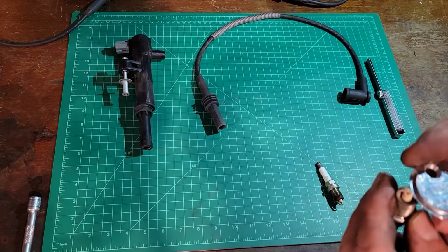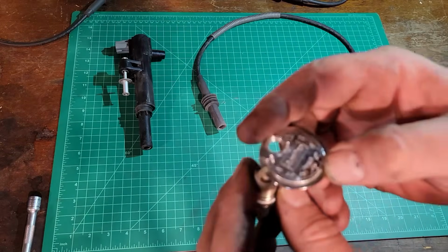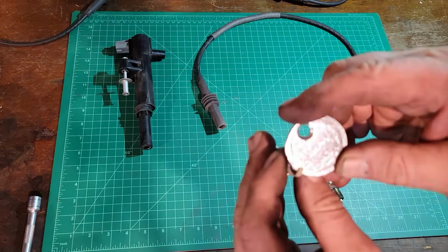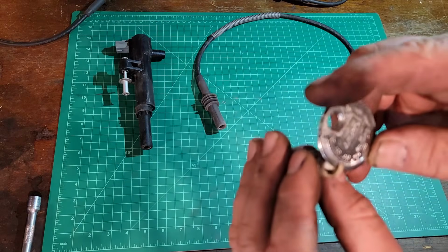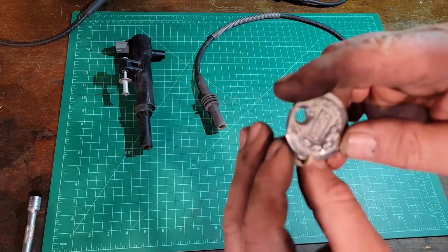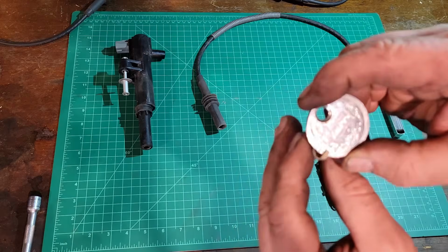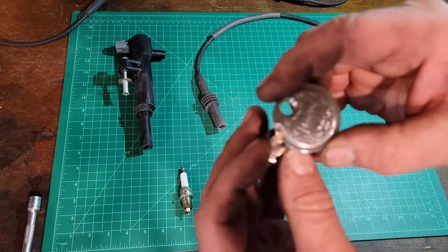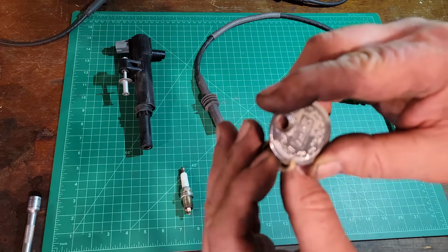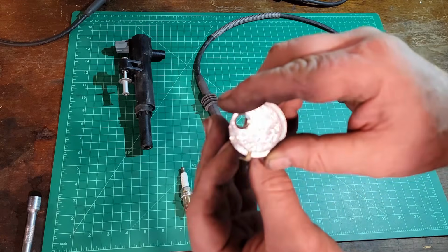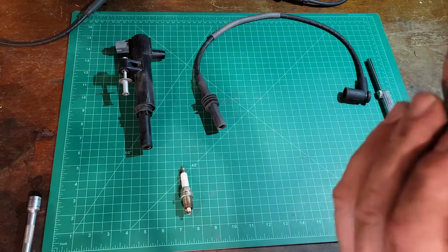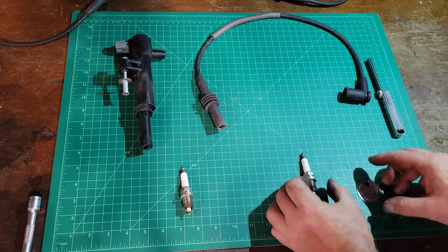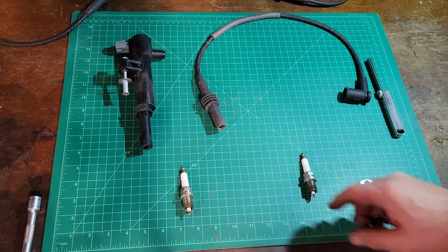Okay, guys, this is the last coil, cylinder number 5 and number 2. We'll call that about 37. And this one would be on the wire. Call that about 36. So it looks like maybe 35 thousandths was what they were going for on the pre-gap.